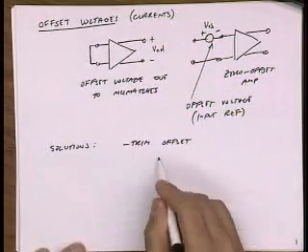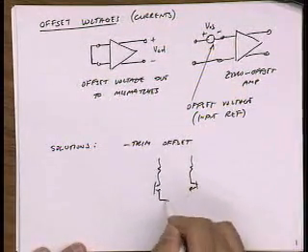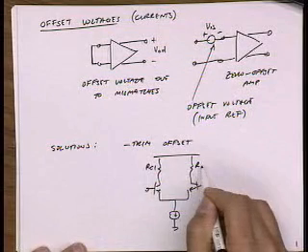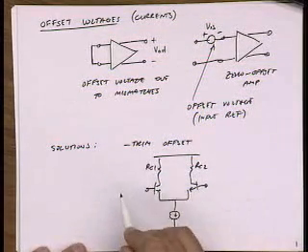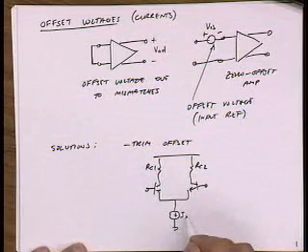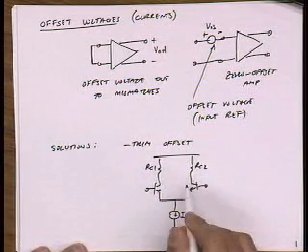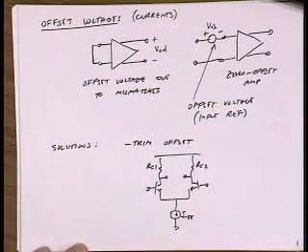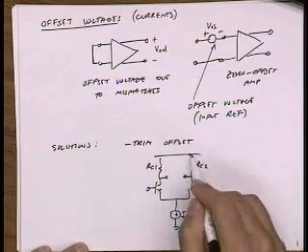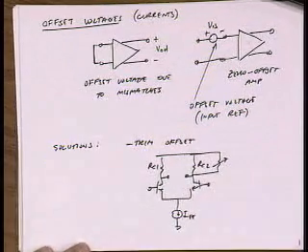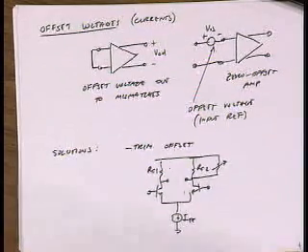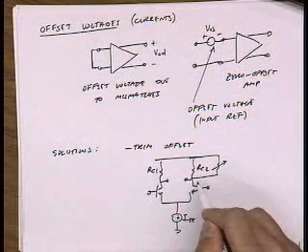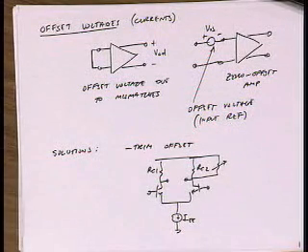Okay, let me give you a simple example. Let's say I have a diff pair, and let's just say that the only offsets are these resistors, RC1 and RC2. Because they're not perfectly equal to each other, even though this current, IEE, splits up evenly, there's a residual differential voltage at the output. Then divided by the gain, that's the input referred offset voltage. So I could just have another resistor here and adjust its value. I can put a screwdriver into my op amp, turn that potentiometer, and get exactly the perfect value of resistance so this is matched.